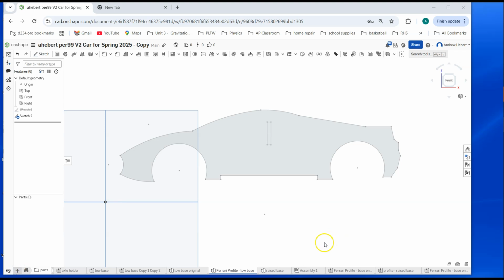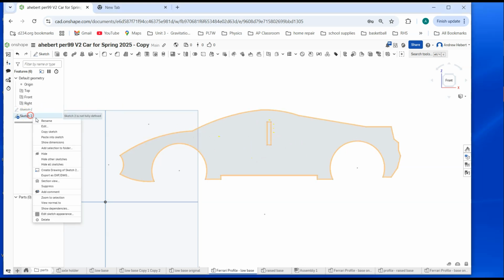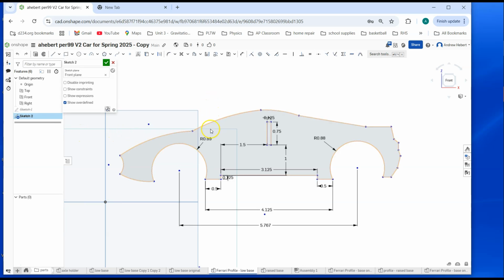All right, at this point, you should have sketched your car with an opening either at the bottom or around the middle maybe, or a little bit above the bottom for the base to insert into, and this slot right here. You want to right click, edit, look at your sketch, make sure you've got this dimension on a curvy wheelbase that looks circular. If you don't have a circular wheelbase, you just need to make sure you can fit in a wheel that has a diameter of 1.65 inches.